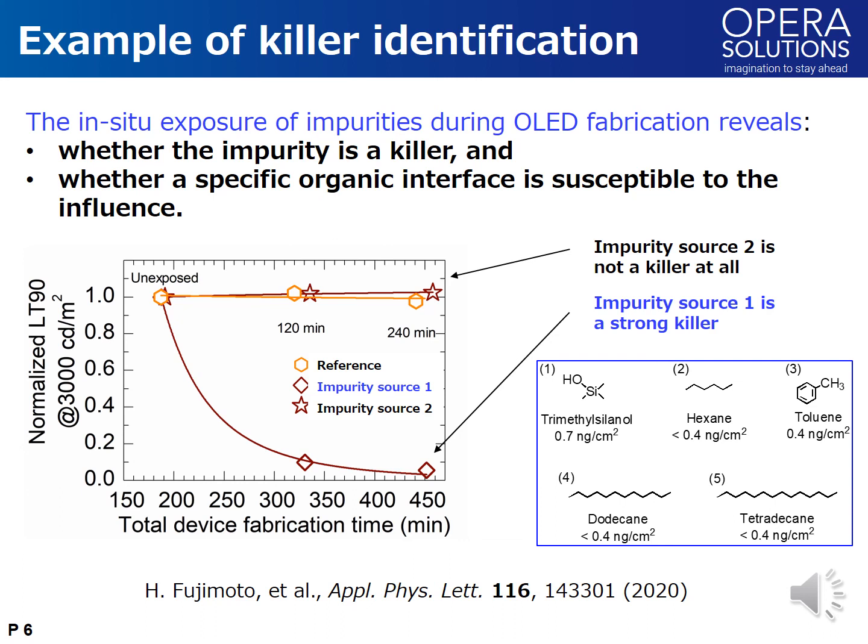In addition to the study of the impurities, we can also study the impact of water present in the vacuum chamber. For this purpose, a cryotrap is equipped to the exposure chamber, which can reduce the amount of baseline water. The advantage of controlling the water baseline is that we can distinguish the two different factors that are impacting OLED lifetimes, namely the impurities and the residual water.